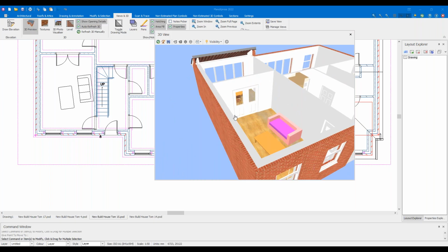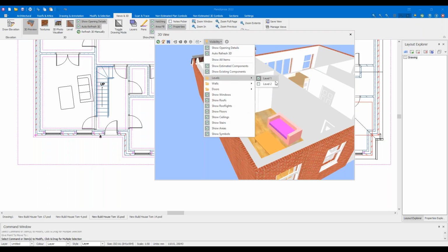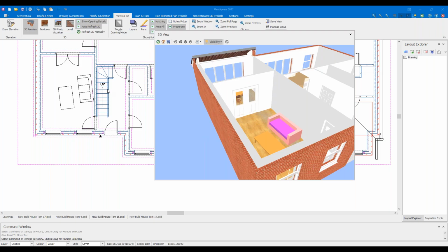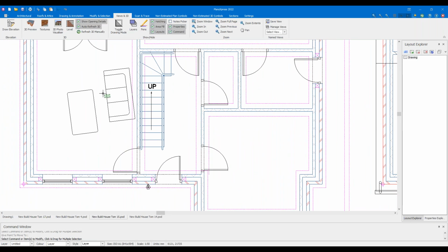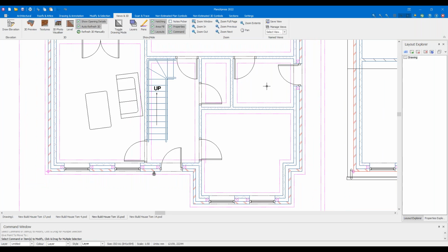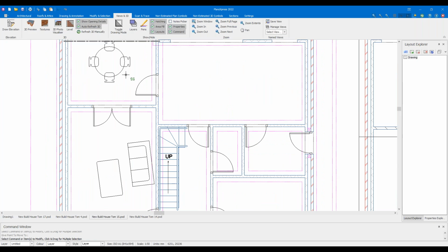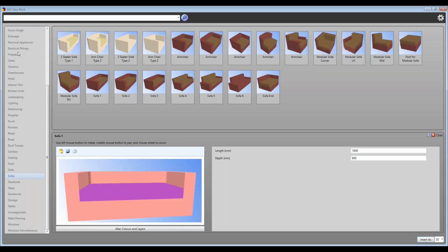We start placing them on the 3D so people can get an idea of how it works. And because they show up as 2D and 3D, you can use that to indicate the style of the room as well. Sometimes you can use these as a way to indicate the purpose of the room better than you would do with, say, a label. Now, a landing or hall might just need a bit of a label on them. Sometimes a WC or a cupboard might need some indication or utility, but you can mark out things like offices, kitchens, dining rooms, such with, say, non-estimated 3D symbols just to show the purpose of the room.